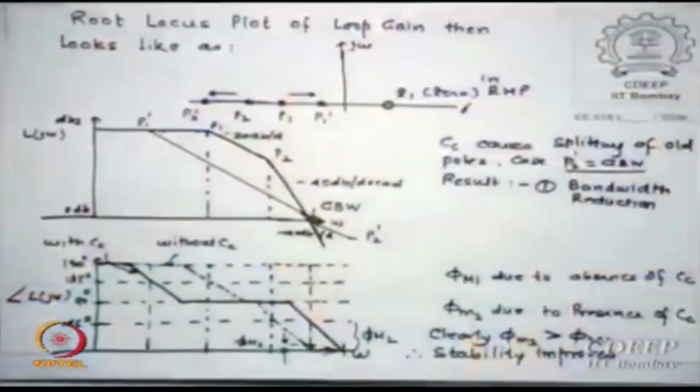If we can play with Z, then I have another parameter for phi m, okay. Now this part is what we say controlling right half plane zeros in such a way that this CC requirement is slightly reduced.